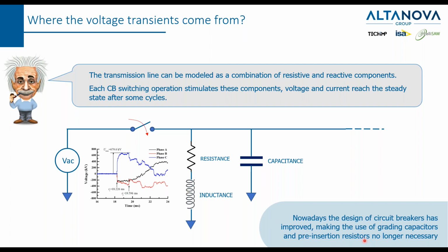But we have to say that nowadays, new circuit breakers do not use grading capacitors and pre-insertion resistors, because the design has improved and they are not necessary anymore. So when you see grading capacitors and pre-insertion resistors, maybe you are in front of a quite old circuit breaker.